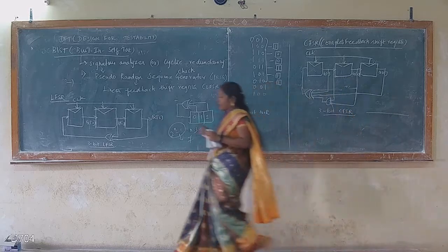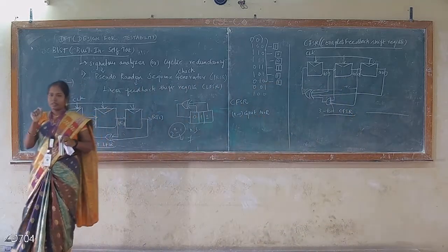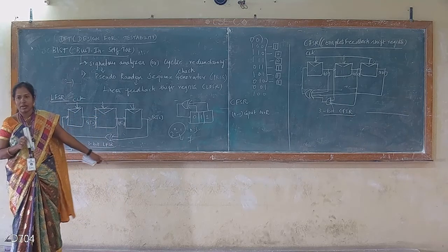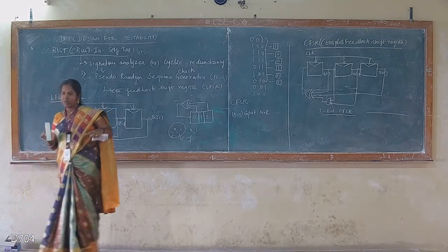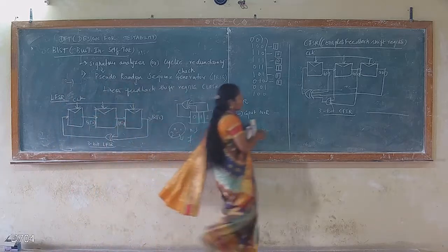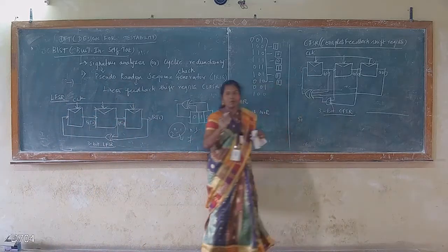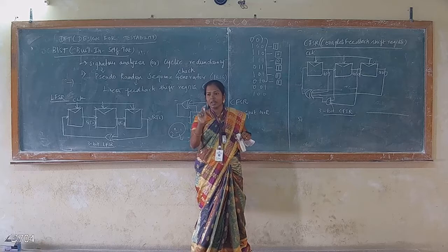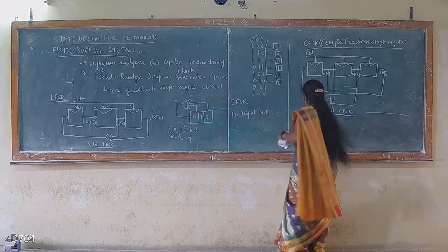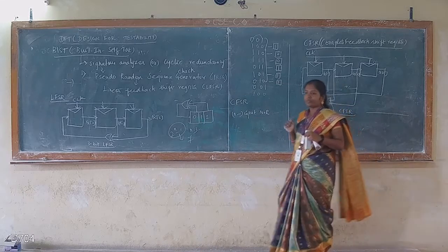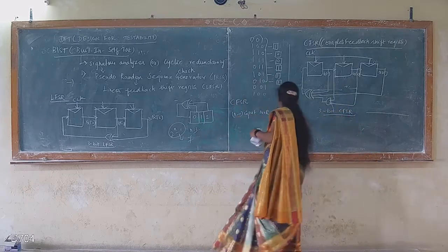Already I said that for testing we generate the test patterns by using a pseudo random generator. Then we apply this input to the combinational logic. At last the signature analyzer will get the input from the combinational logic. Then we will calculate the syndrome. For the BIST process, first we need to reset the syndrome to 0.